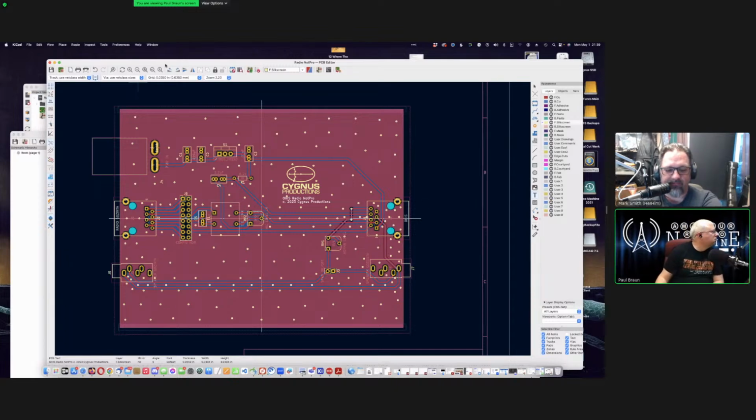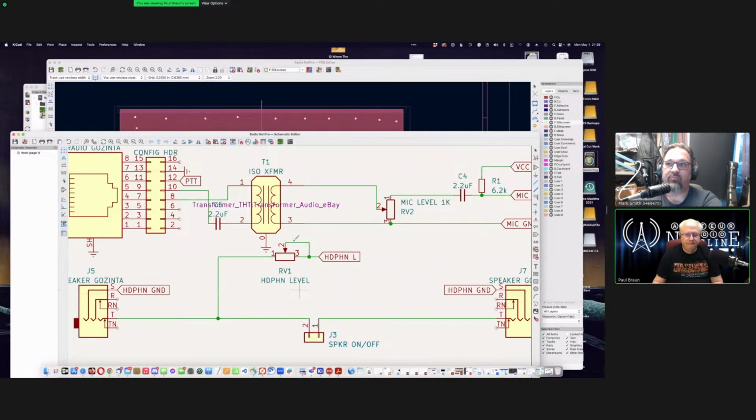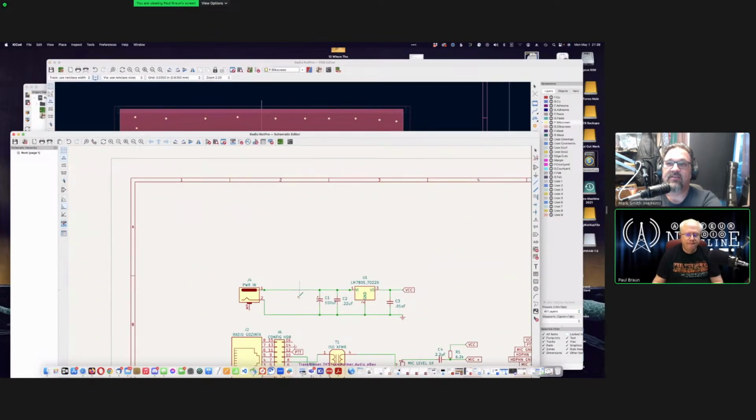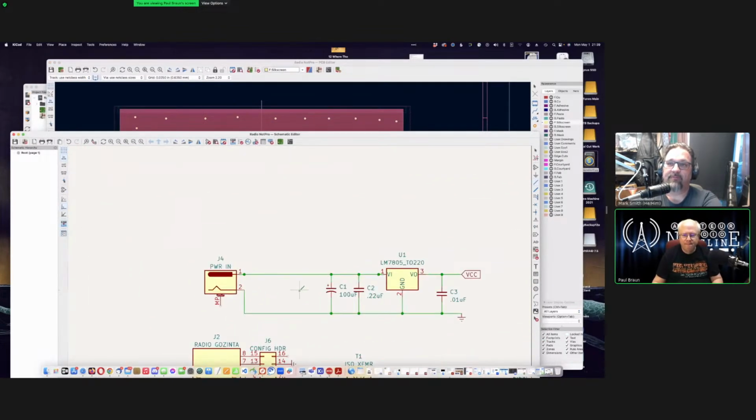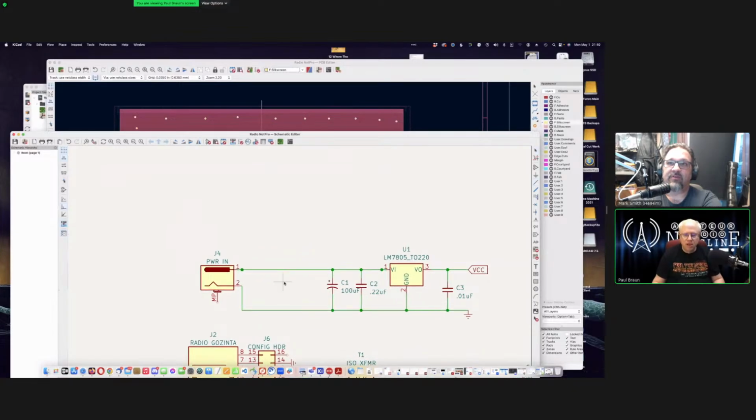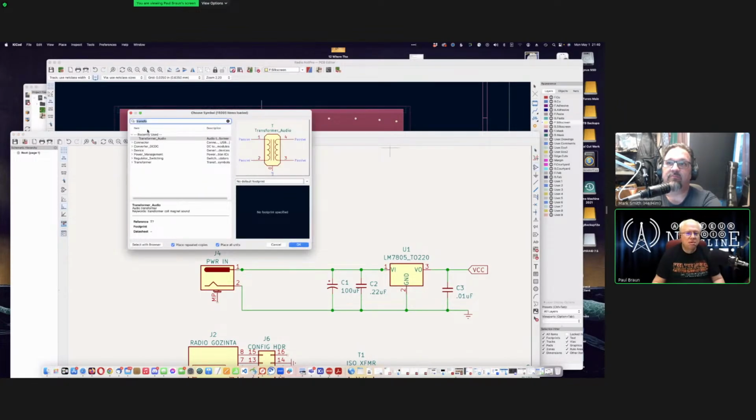Please forgive me for butchering the pronunciation of your name. This is not a name I'm used to. I think it's Emra. Thank you. What Emra is suggesting is putting a reverse bias diode across the input of your DC. So a diode pointing up, so that it will not conduct in the normal mode, but will conduct if it's plugged in backwards.